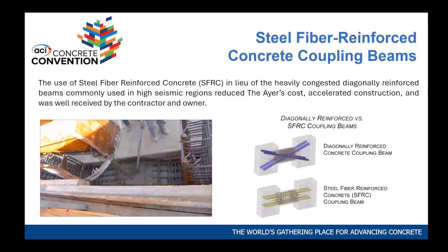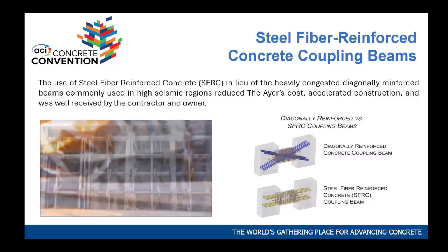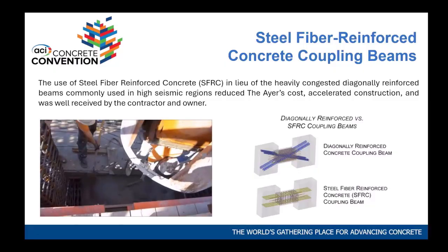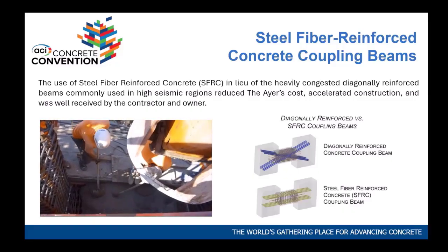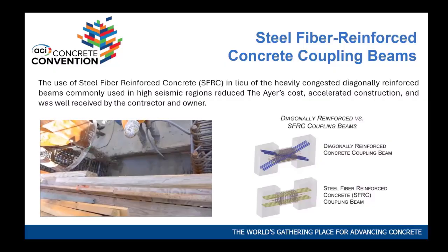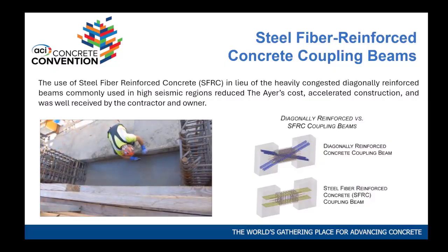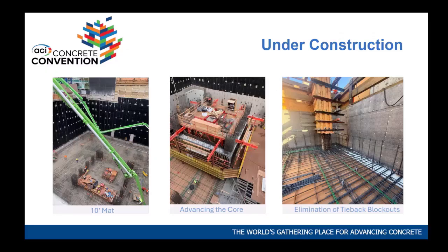It's interesting, we use the SCC mix. When you put the fibers in, not because steel fibers suck water, they don't, but it turns the SCC mix to a 6-inch slump. You have a 27-inch slump for a self-consolidated mix, and you put these fibers in, suddenly you're down to 6 inches, plus or minus. But they're all over the mix, you don't see them when you strip, so it's a pretty neat thing. We've done about 15 buildings like this throughout.